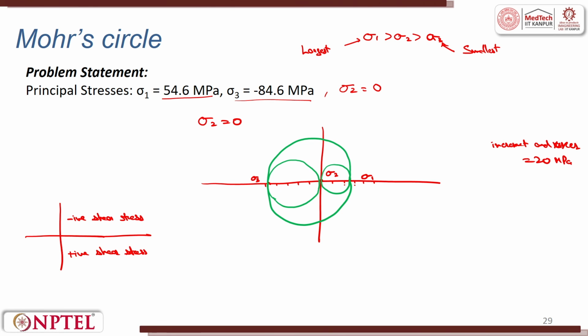So, this represents my Mohr circle. I can again plot the pointers here. This means 3 Mohr circles can be drawn, each based upon 2 principal stresses. Sigma 1 and sigma 3 represent one circle, the bigger circle, which I will call circle 1.